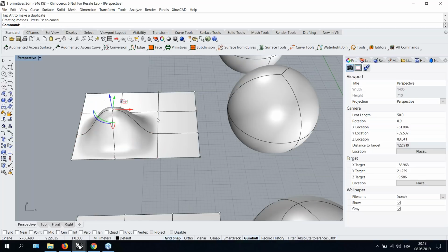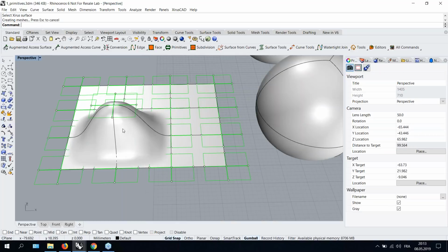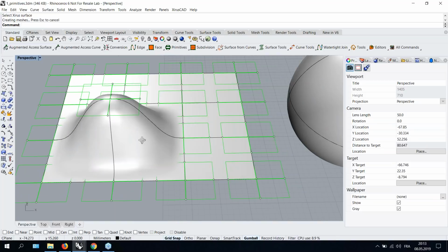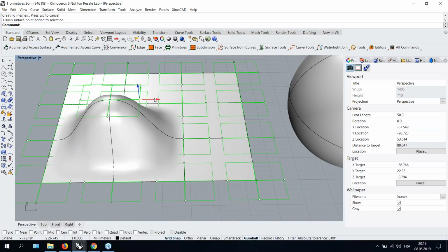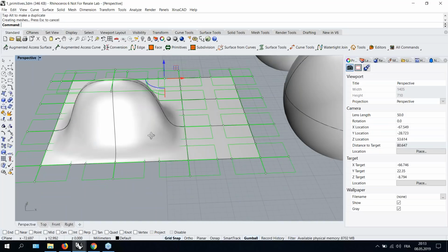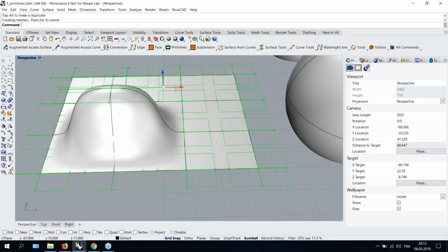And then another particular thing about basic shape control is, for example, the tangent control that we provide. Here you can see that you can display the tangent planes at every control point. Now, if I move one tangent, you actually don't move the control point itself, but instead you can control the flatness around the control point, or also the sharpness.